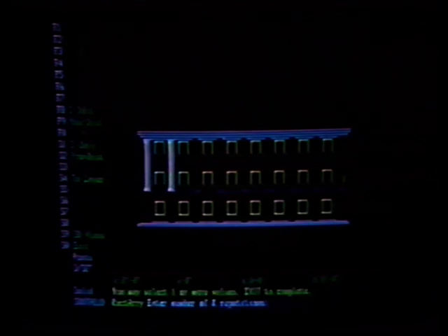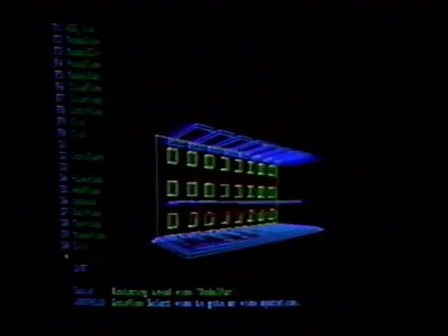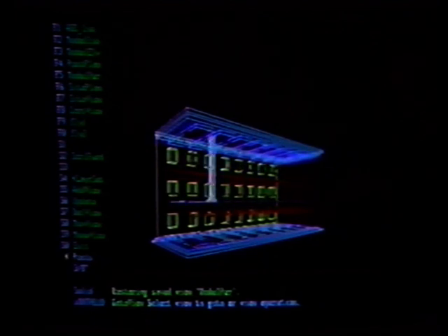Or I could say, let's create a whole array of those columns 8 feet to the right. And here I'll have 8 columns across and 1 column down. Select the entity, and I end up with a whole facade of these round columns. And because DataCAD's system is interactive, not only are these columns positioned in the elevation, but I can go back to other views, like a perspective, and see the model that I had drawn prior to the demo with the addition now of the new columns in the order that I drew them.